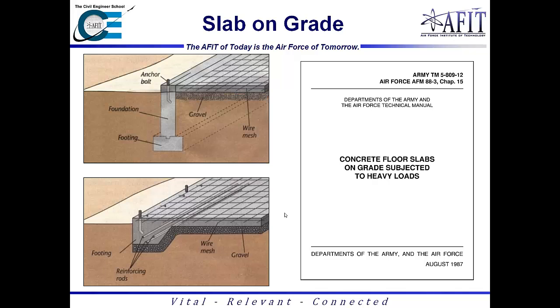I think it's going to be more like, with wire mesh, where does the wire mesh go in the slab? The answer is wire mesh goes closer to the top because wire mesh is meant to prevent cracking. However, if I was going to make this a reinforced slab with actual rebar, the rebar would have to go towards the bottom where more of the tensile forces are.